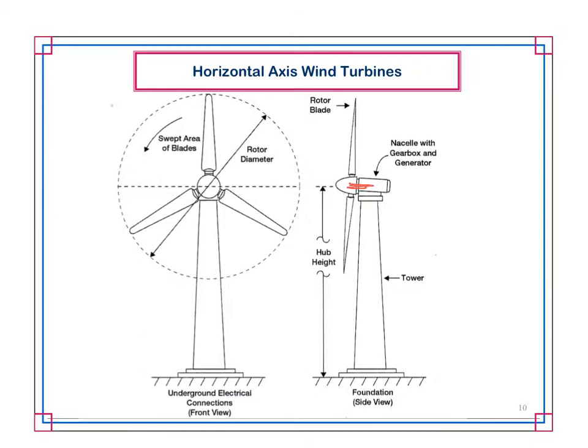Do those guide wires limit the density for vertical, like, because the wires are literally in the way of where you could place the other ones? Yeah, so the question is, do the guy wires impact the location of the other turbines? Absolutely, but you could rotate where the guy wires are located, because you just have to space them 120 degrees. So you could actually rotate them, and you could get them almost on top of each other as long as they're rotated correctly. So they don't actually have to be next to each other. You can rotate them, so as long as they don't impinge upon other turbines, then you should be fine.